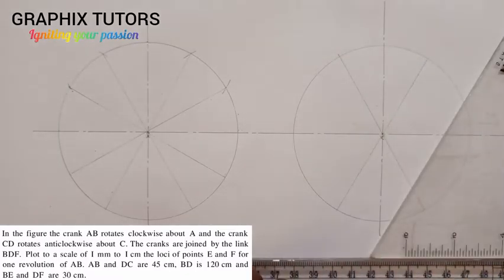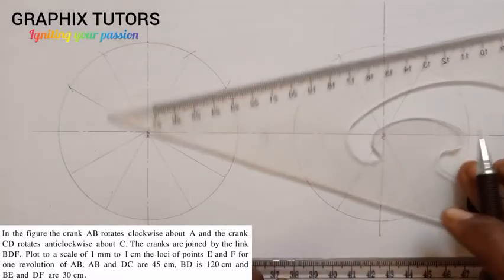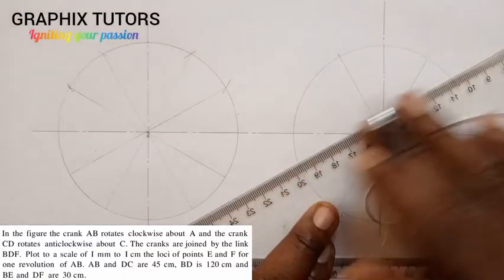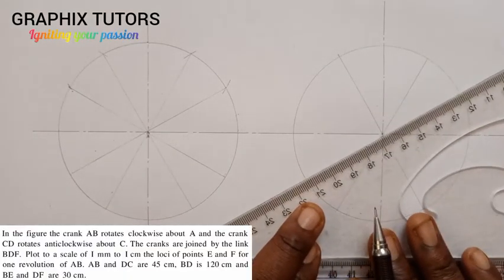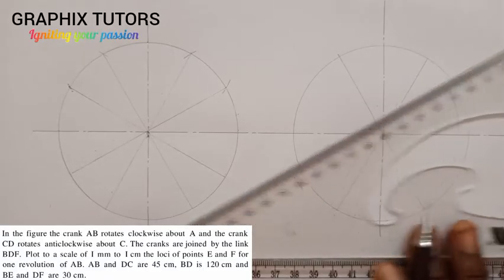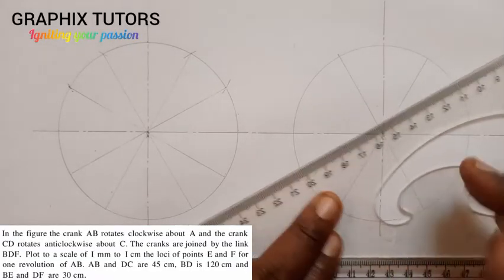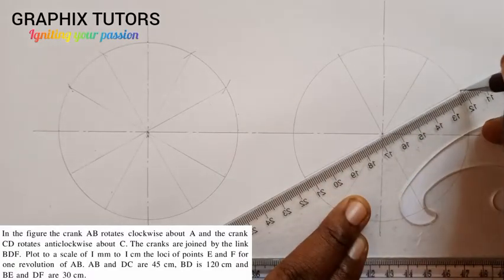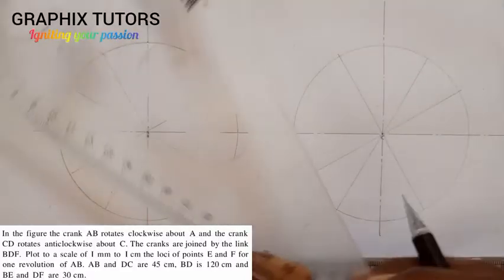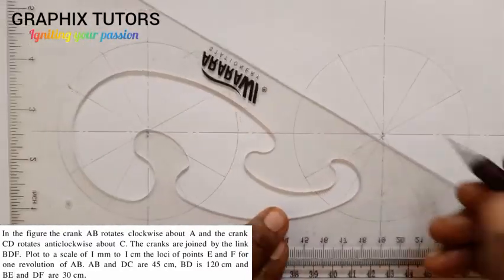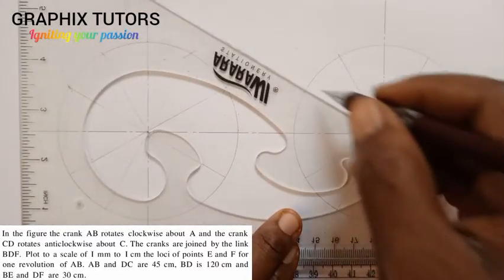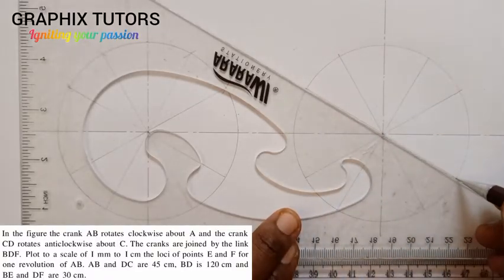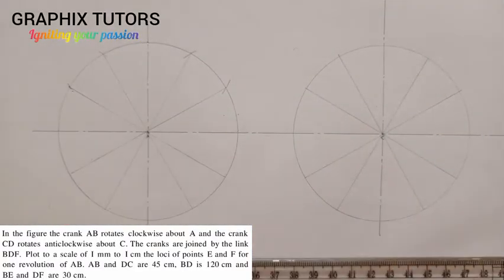After doing that, I'll set it down this way using the 30-degree side here to draw. Ensure that it is tangential to the square. So place it here and I'll draw. Then I'll turn it the other way around also, place it here, and draw. Now this is it. You can see there are two methods that we can use to divide a line into 12.